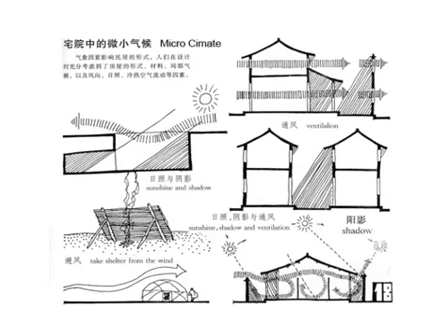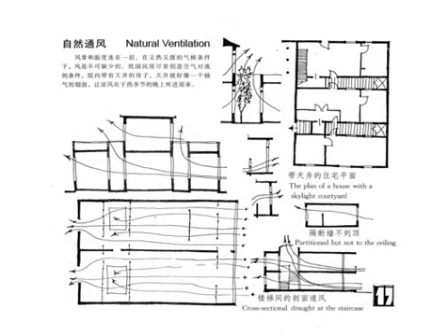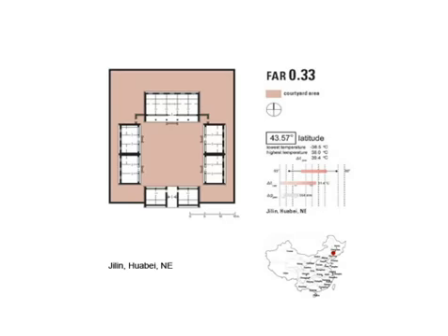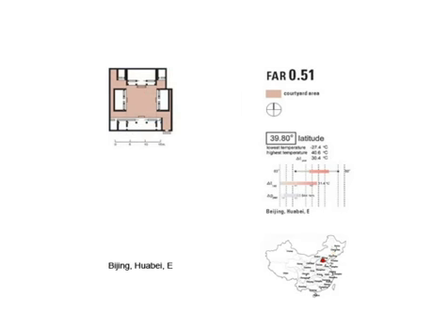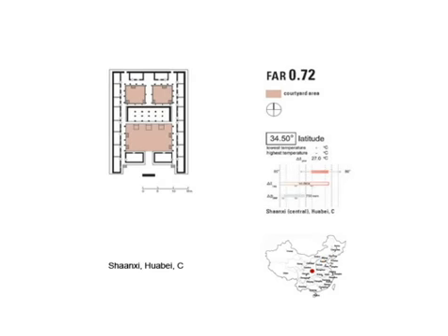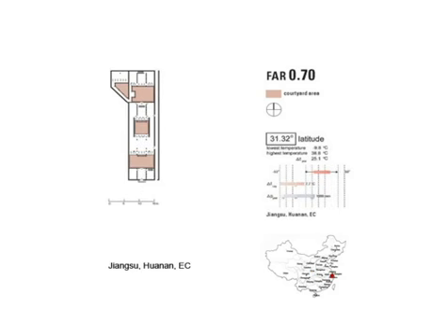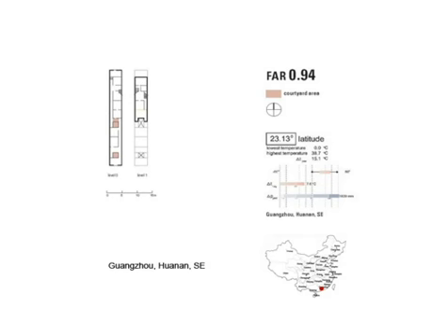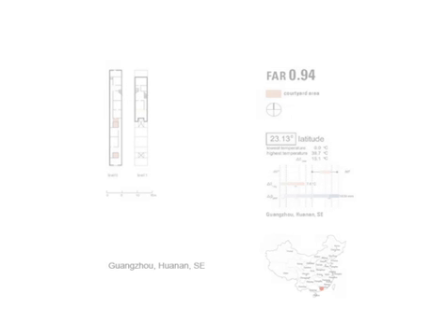One of the main forces that generates the organizational difference between Chinese courtyard houses is the climatic zone in which they are constructed. Depending on its location and local climate, the courtyard type changes its organizational structure from an enclosed landscape composed of freestanding houses in the north to very small light wells in the south. The type's geometry is driven by outdoor spaces for climatic purposes. In the north, the courtyard acts as a passive heating device, while in the south it performs as a solar ventilator.